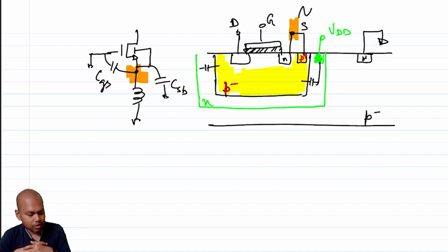So this is usually another trade-off. Let's take some very crude examples. Let's say your FT of the transistor is 100 gigahertz, which is actually quite common in today's technologies, and you are operating at a couple of gigahertz, maybe 2 gigahertz or 3 gigahertz or even 10 gigahertz, you are fine.